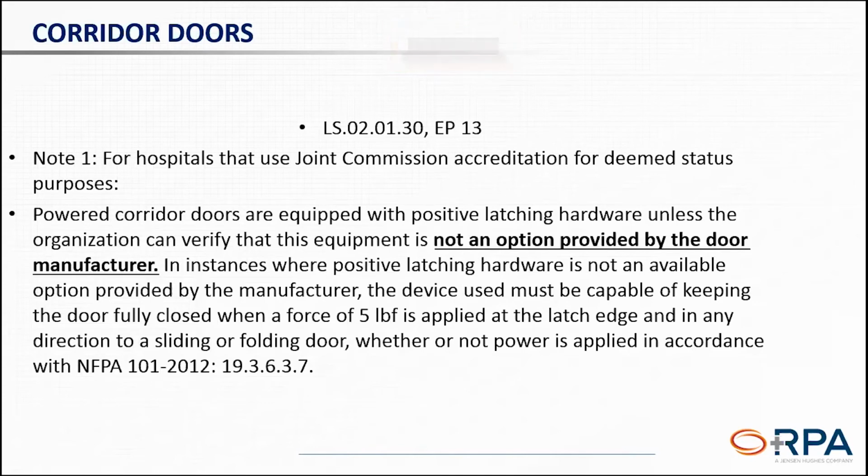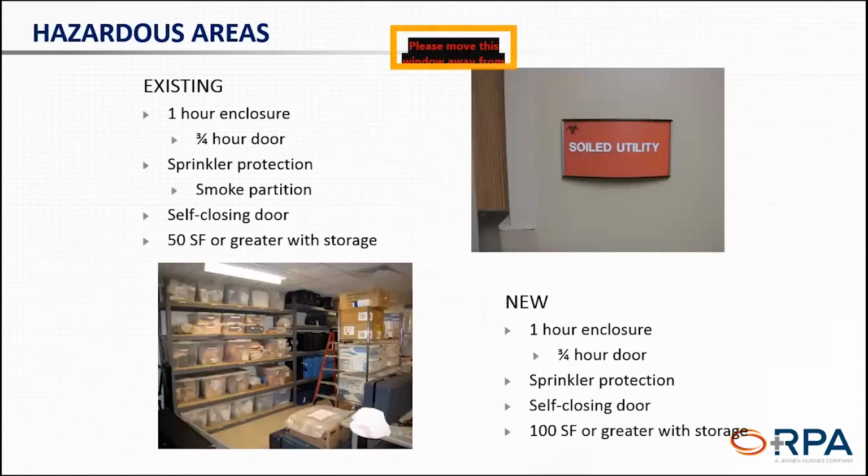So I suggest doing a round through your building, using your life safety drawings to identify where your suite boundaries are and where you're potentially hung up for that type of situation.